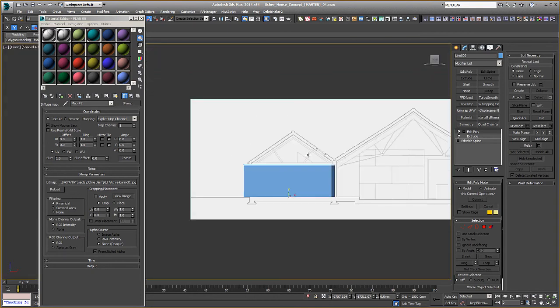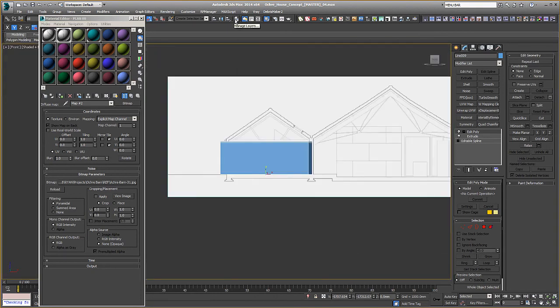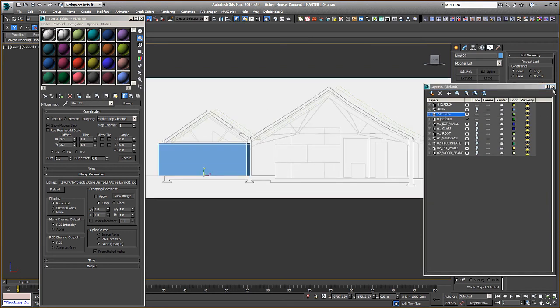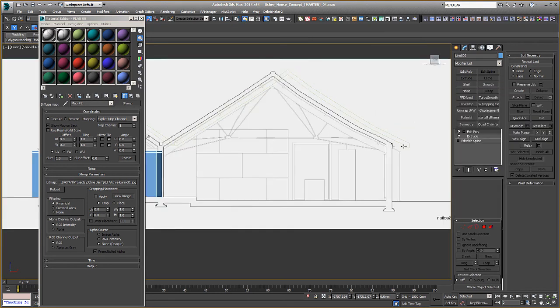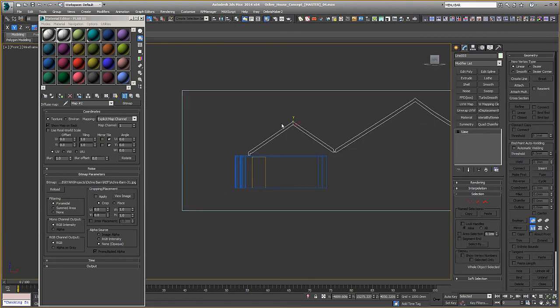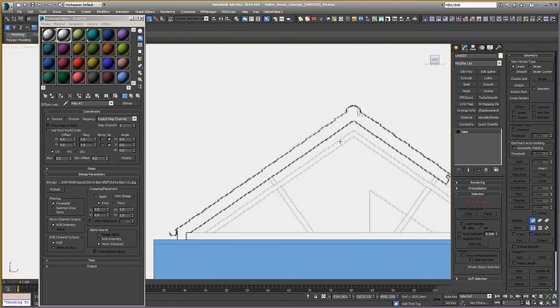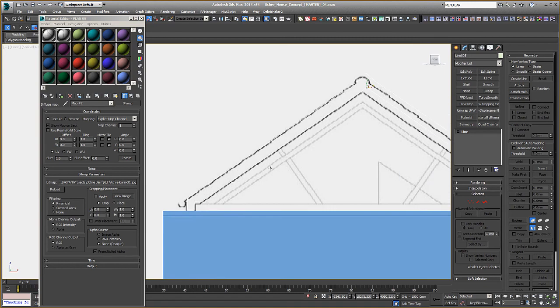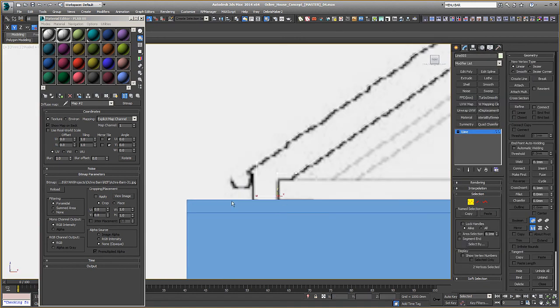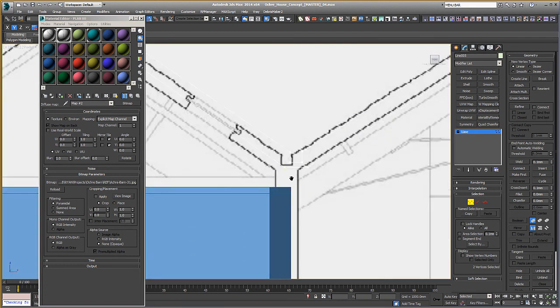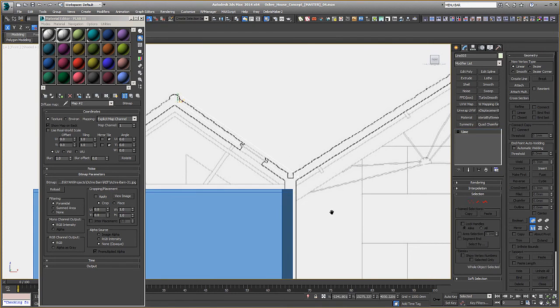Now, having previously modeled this before, I have a spline reference. Everything's a little bit off zero from before. So I've used the same technique as the walls, but I've gone through and I've drawn a spline for the roof, sorry, not the ceiling. And I'll bring these down to meet the walls, and we can snap these. That'll help us later with light leaks. This wall's a bit higher in the middle, so